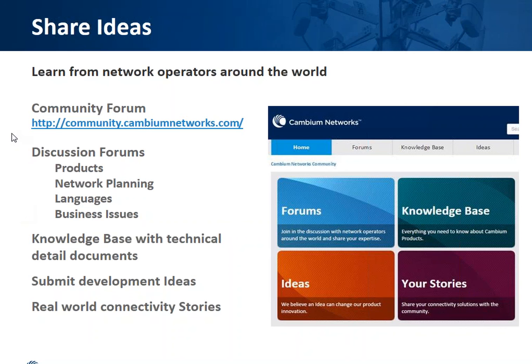As I mentioned, there are some other antenna manufacturers working toward developing solutions, including things like a dual slant flat panel antenna that may be an option for you if you are unwilling to try a Yagi because of the snow and ice buildup. There are also some wrappers or covers that I've seen in third parties that could be used to cover that antenna without affecting the RF signal to maybe shed ice a little bit better. But yes, there are some potential issues with that as well.